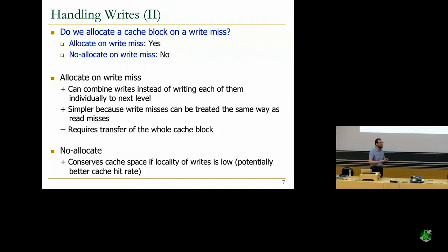You can decide not to bring the cache block into the cache. If you, for example, say, oh, I'm doing a random read, and I don't have good spatial locality. But this requires some prediction mechanism now, right? You need to be able to predict whether you will have good locality or not. And existing cache policies are actually much, much more complicated than what we've discussed. They do things like that. But we don't have time to cover them.